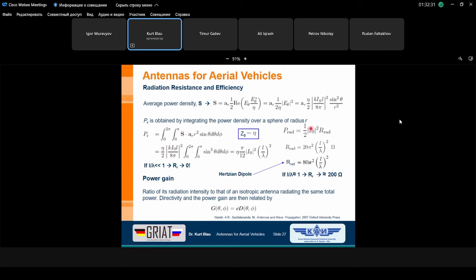This is important to mention: if we excite the dipole with a sinusoidal voltage, this is the peak value we have to insert, and if you want to know the average power, then it's the half. The mean value regarding the maximum is 1 divided by the square root of 2, and squared, 1 divided by the square root of 2 squared is a half. This is the explanation for the factor 1 divided by 2.